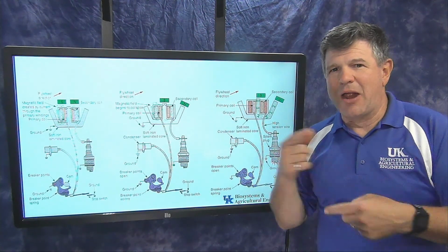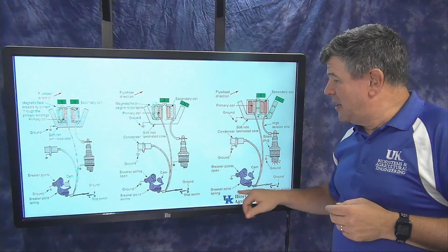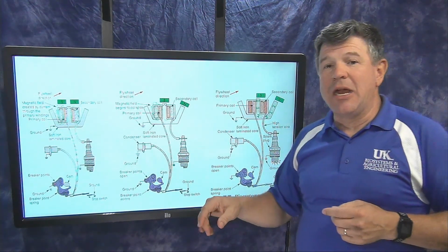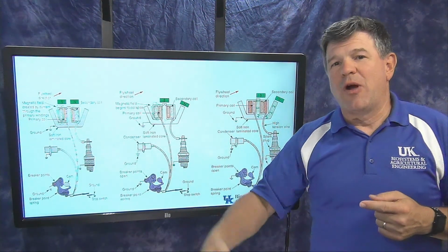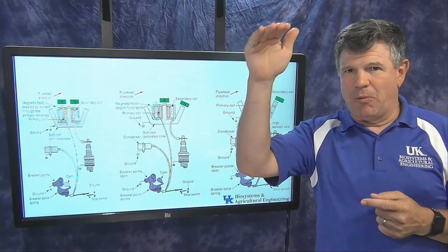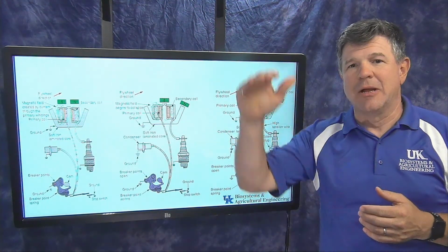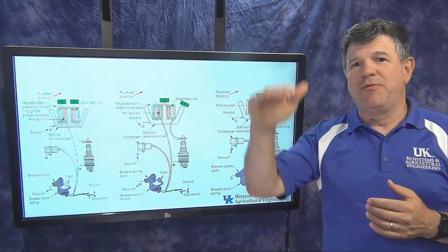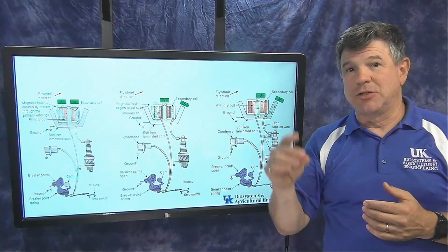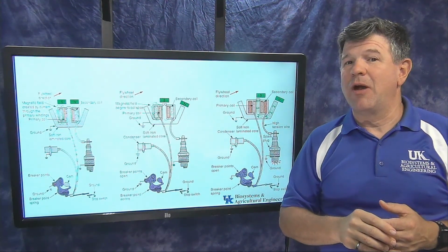So you can think about how fast this happens too, because again, this crankshaft is rotating. For every 2 rotations of the crankshaft, we have to have a spark. Remember, we've got 1 power stroke on a 4-cycle engine. So thinking about this as a 4-stroke engine, on every 4th stroke, we have to have a power stroke, so we have to have a spark. And that happens on every other crankshaft rotation.